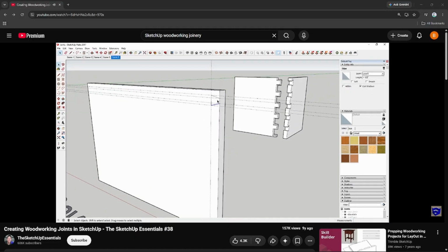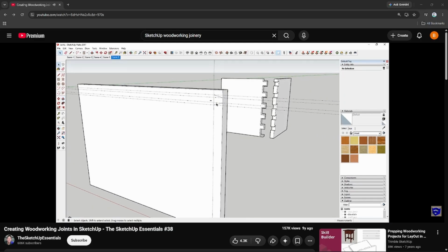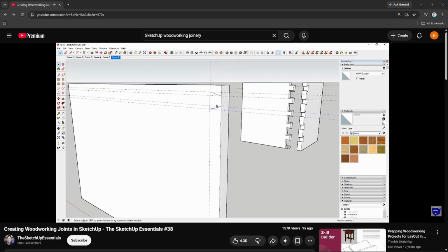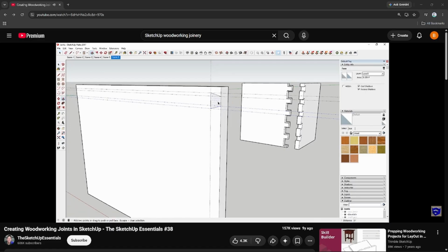And when I did that, I didn't really necessarily like the way that that looked with how thick this little piece was right here. So all I'm going to do is I'm going to come in here and I'm actually going to move this, and I'm also going to move my measurement points down by probably 1/8 of an inch. And so that's one of the nice things about SketchUp, is you can select this stuff and you can move it down just like that, and so you can adjust this stuff really easily.